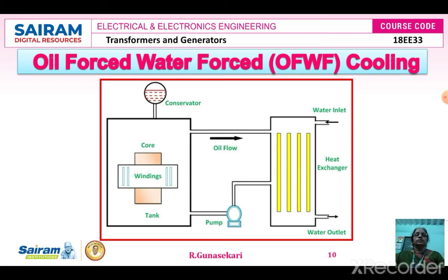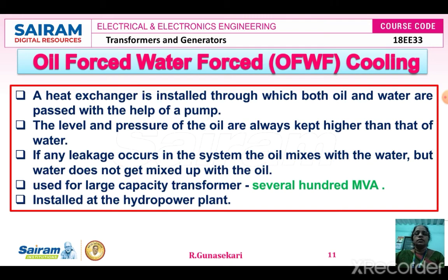Now you see the key points. A heat exchanger is installed at the outside of the transformer tank, through which both oil and water are forced with the help of the pump. Usually the level and pressure of the oil are always kept higher than the level and pressure of the water.